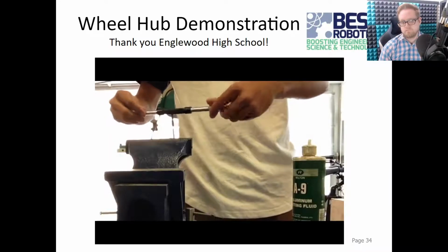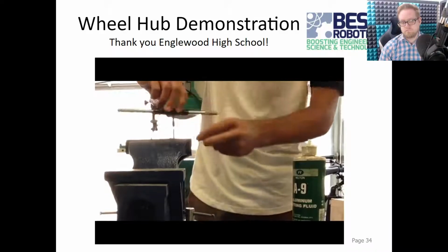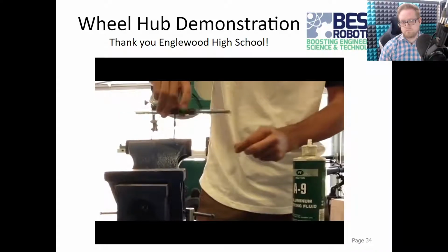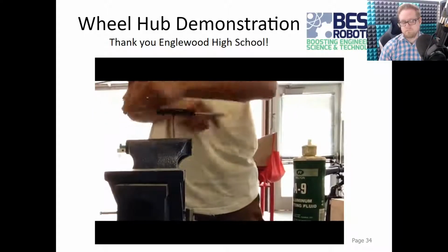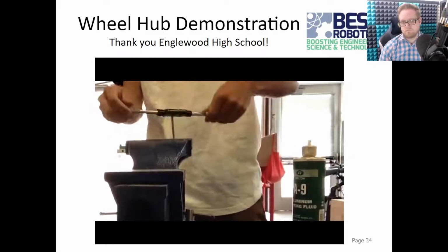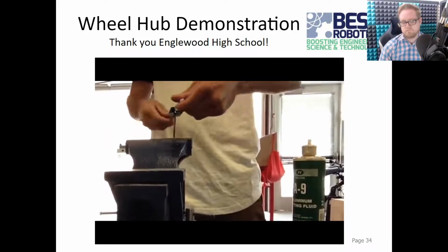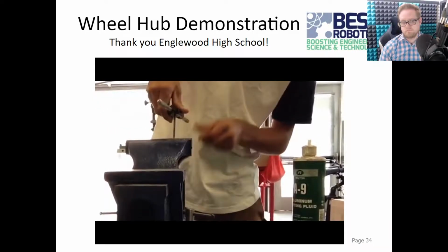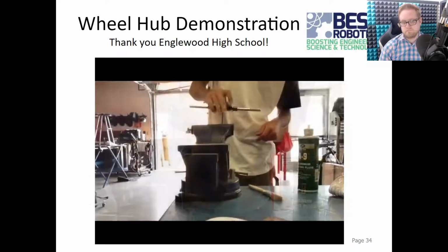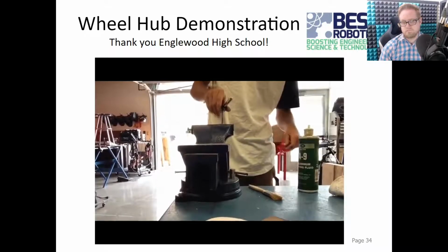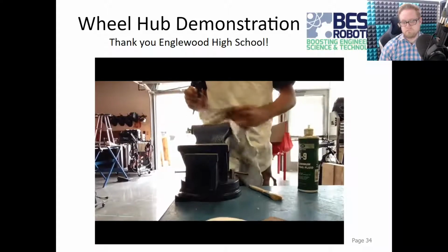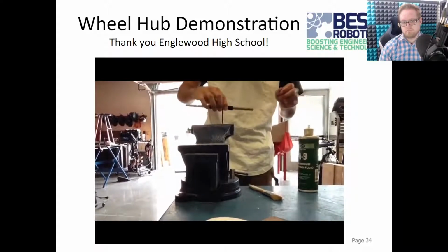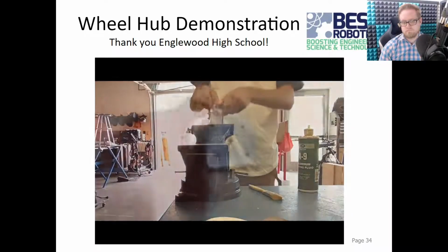Place the tap in evenly. Turn the tap clockwise. You're going to do this until you feel pressure. It may take a while, but you're going to have to back out the tap every once in a while to clear it off of debris. As you can see here, I'm reversing it to pull it out and clean the threads off. Clean the hole again and then insert and turn clockwise again.